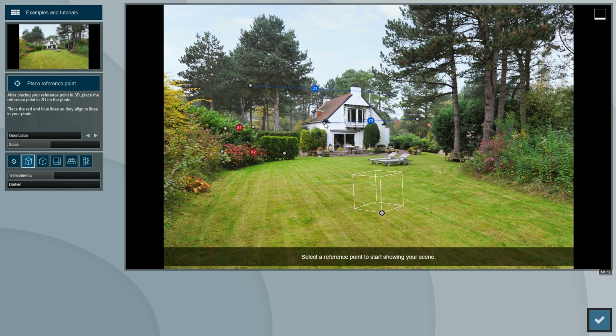The next step is to repeat the process we saw in the example using the new photo we loaded. Luckily, the house in our photo is made up much like a cube, with walls that are perpendicular to each other, which will perfectly represent the perspective of our photo. Let's place the blue and red axis lines on the house of this photo, making sure that the lines of the same axis are pointing towards the same vanishing point. Doing this accurately is crucial to get our 3D model to match and fit nicely within the photo later on.